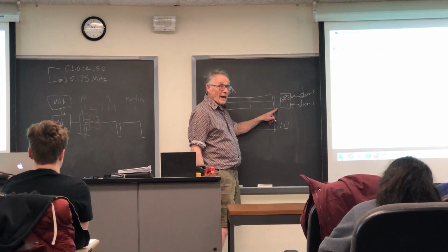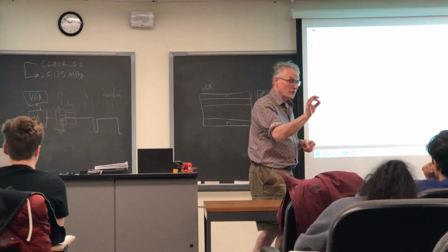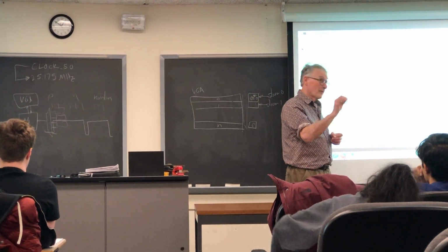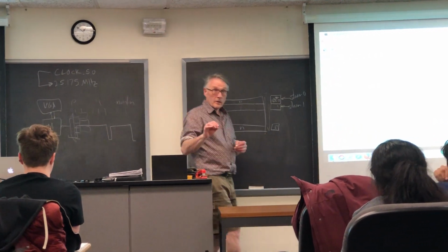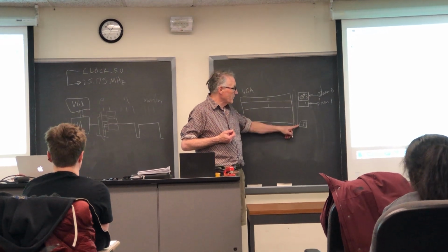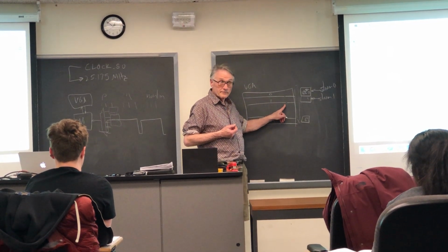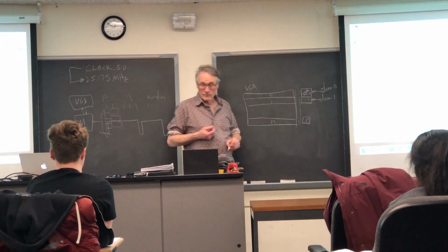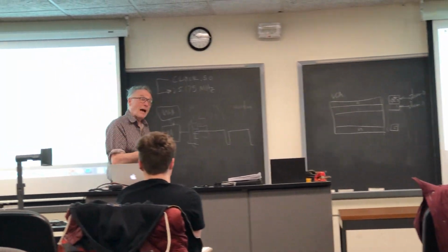The muxing is at the output, but since you know the order in which you have to traverse memory for the VGA output, you don't have a conflict on this side between serialization, because the VGA is, in fact, serial. So I think this will suffer from the same parallel serial bottleneck, just in a different spot.